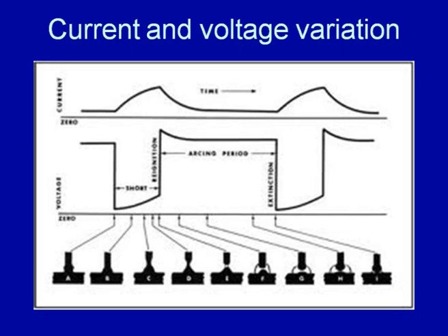So, this is the first situation when the molten metal drop just touches the weld pool. There is a sharp drop in the voltage and short circuiting takes place. This results in an increase in the flow of current, and as the current increases rapidly in this band after short circuiting, heavy thinning takes place and heat is generated under the influence of the welding current.